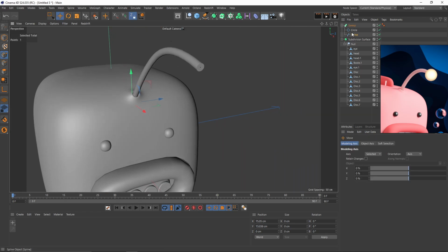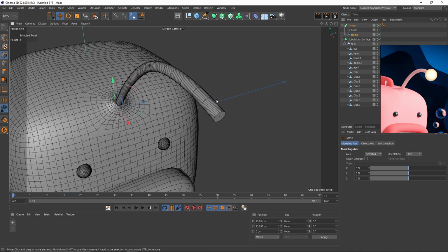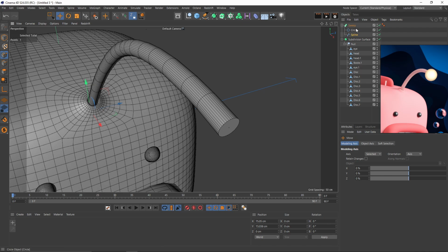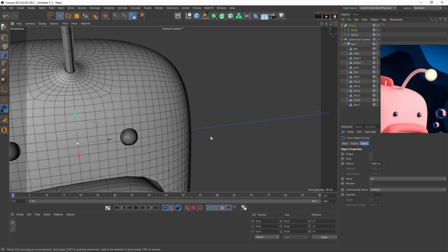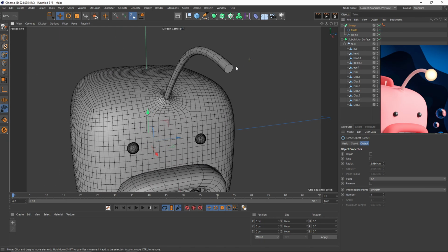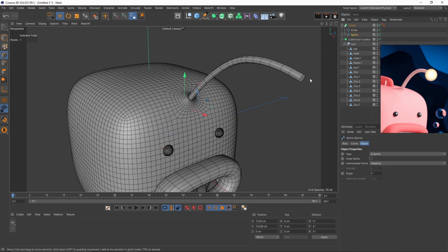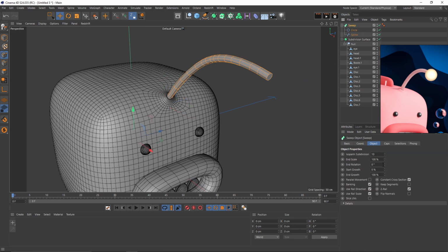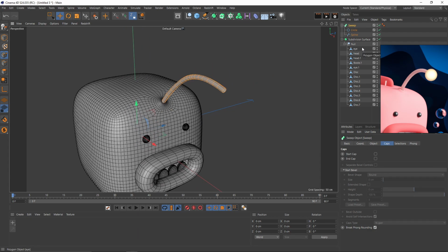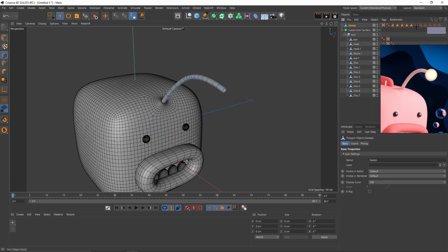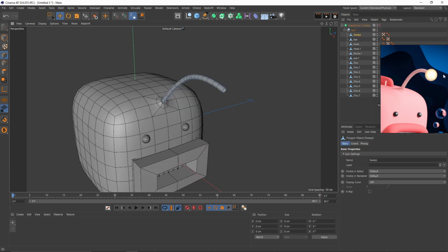Yes. I will enable lines. I think I will have a lot of polygons on the spline. We will not need these. Let's go to circle and change our number to 1. Yes, 1 will be enough. Spline is okay. I can keep that. Also, we will not see the caps, so I can turn this off. Let's make that editable. Make the selections. Then we have this ball.